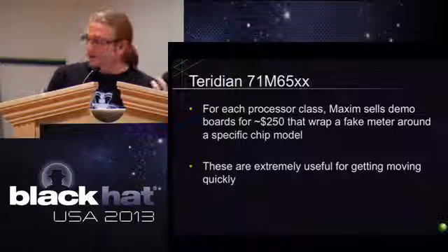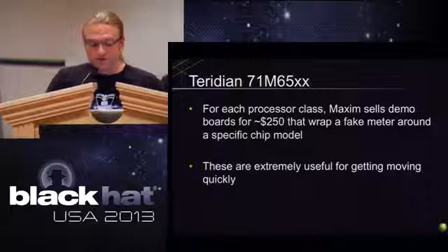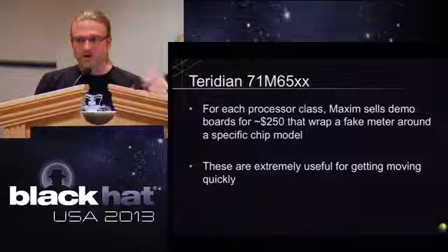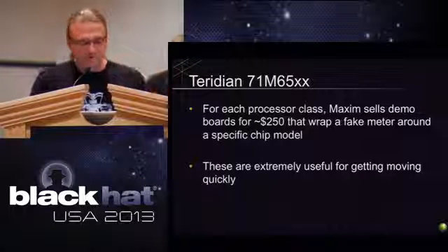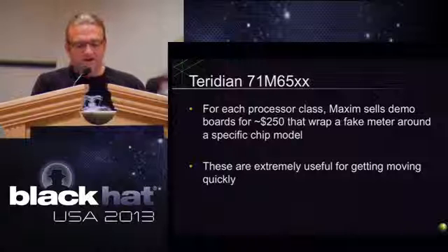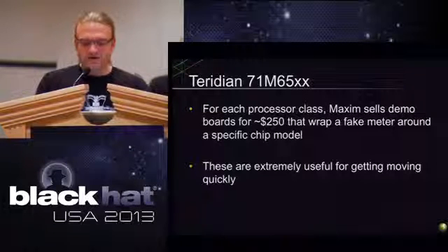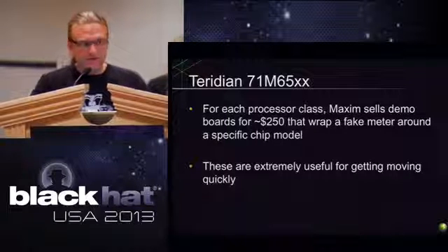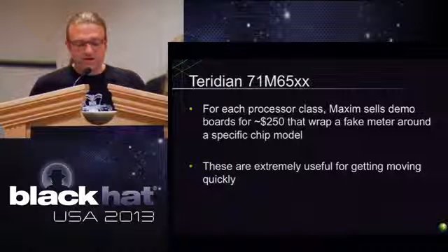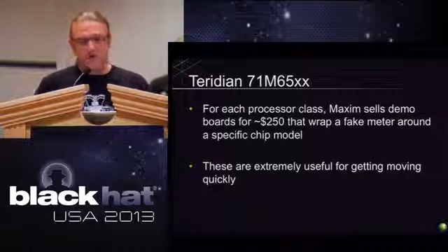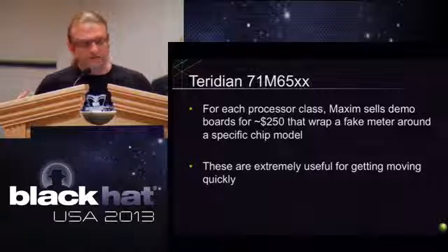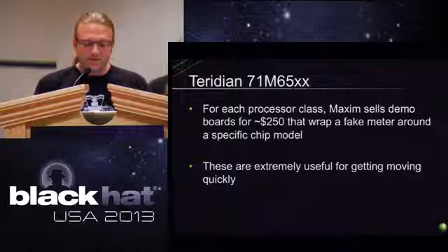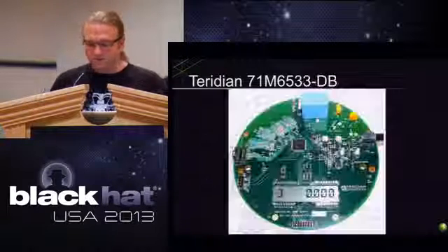A couple more pro tips. If you ever start poking at an SoC in general, Teridian is wonderful about this. They have dev boards where they're trying to sell big vendors millions of these chips to start building hardware with. So they make a demo board that has great open source code, kind of open source hardware. They're relatively cheap, and the whole chip is already broken out completely. There's nice code so you can start figuring out what the chip is doing, at least as far as the vendor. So if you have a specific target, you at least know what reference they started with, and you can look at the board, which here's a demo board right here.